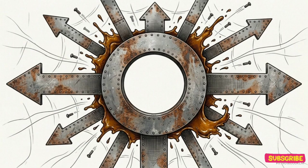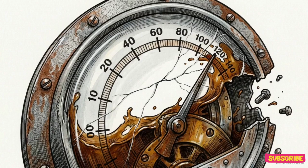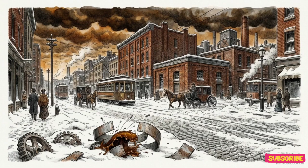Engineers refer to this constant outward radial force acting against the walls of a cylindrical vessel as hoop stress. Even under static conditions, the immense density of the liquid pushing against thin steel and localized rivet points meant the structure was already operating at the limit of its hoop stress capacity. The breaking point arrived via an external environmental variable.